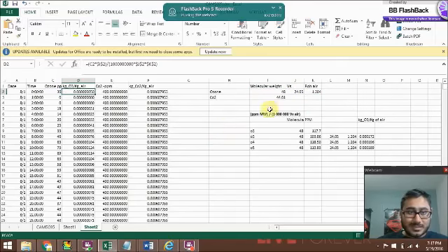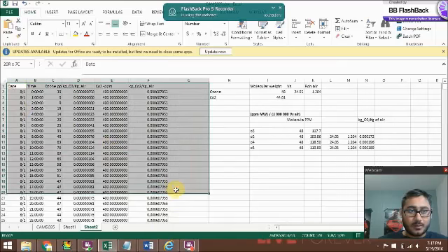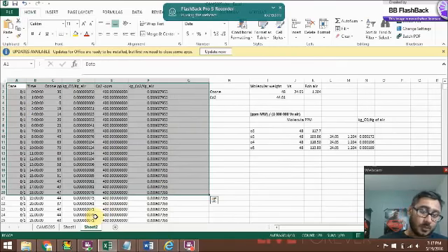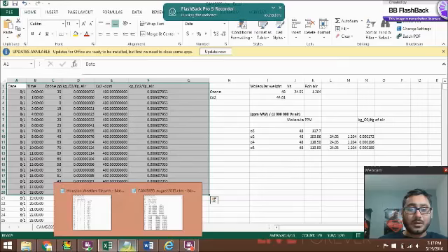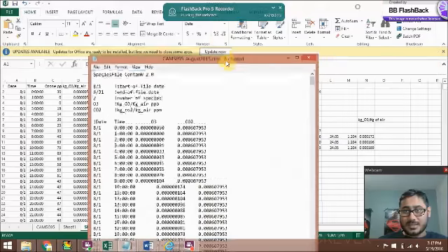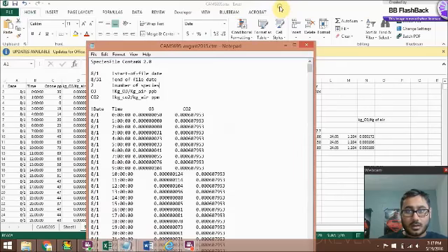So once this is set up, you can directly copy the entire file to Notepad, or you can convert that into a CSV file. So the extension for contaminants is .ctm, and the file contains a header, the start date of the contaminant, the end date of the contaminant, number of species present for the exterior.